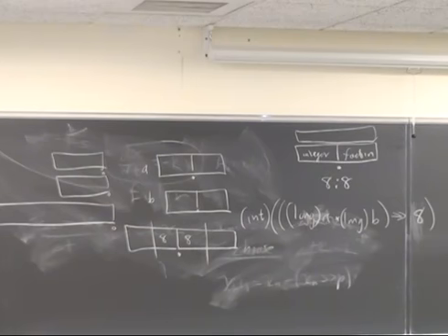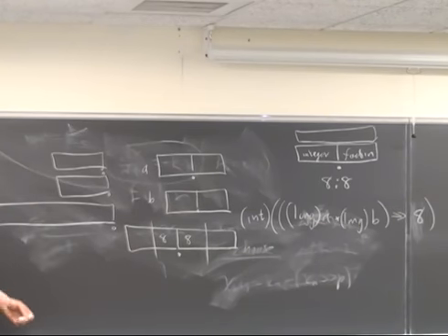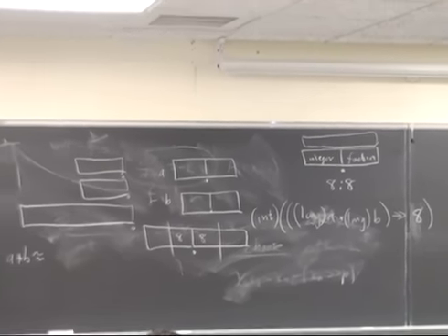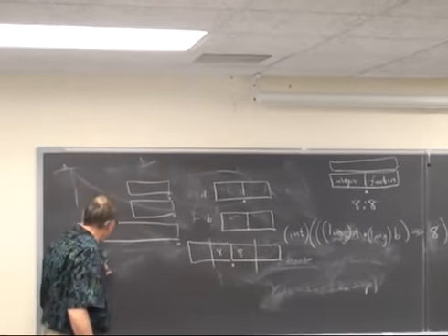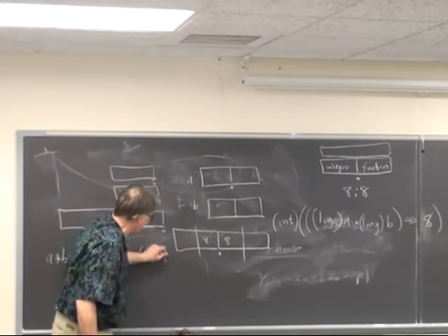But that's fairly slow because then you have to do a 32-bit multiply. It's a mess, and it's fairly slow. So what seems to work? What we're going to do here is not mathematically correct, folks. But what works, and it's really cheesy, is that A times B is approximately equal to A shifted to the right 8 times B shifted to the right 8.